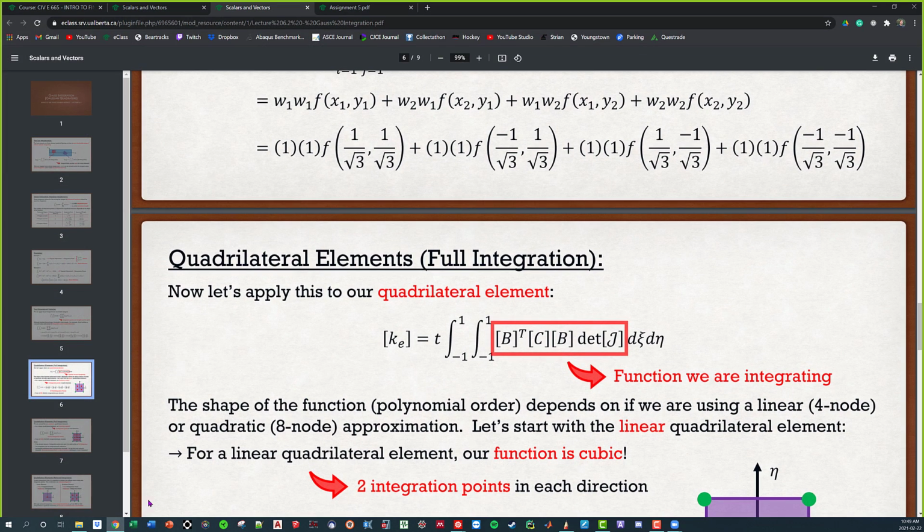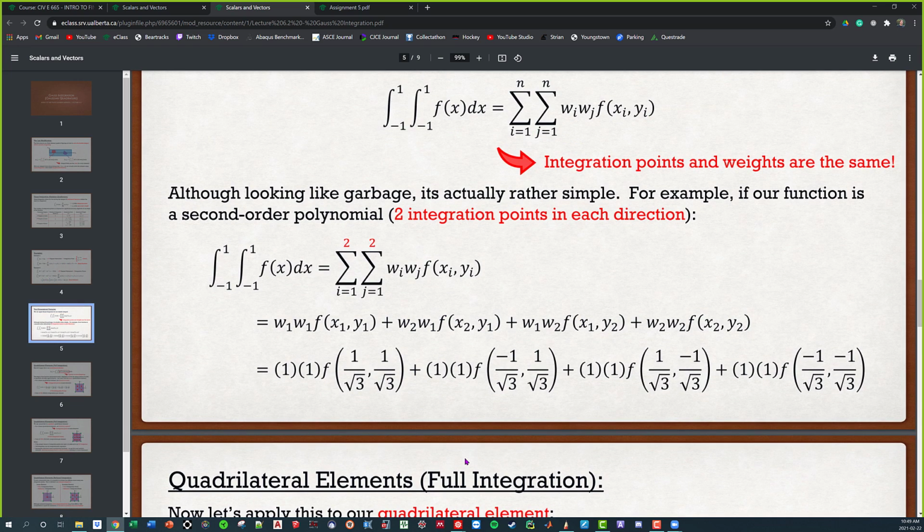So I'm going to come back here, and I'm going to go to this slide. What did we forget to do for the reduced integration? I'll give you guys a big hint. When we figured out for two integration points, we had our function, but it wasn't just our function. It was something else. Sabrina's right, weights. So for 2 integration points, our weights are always 1.